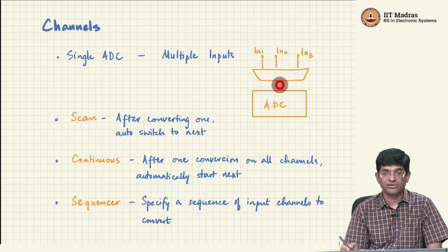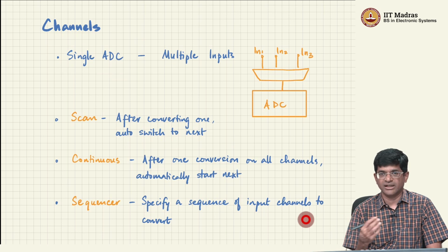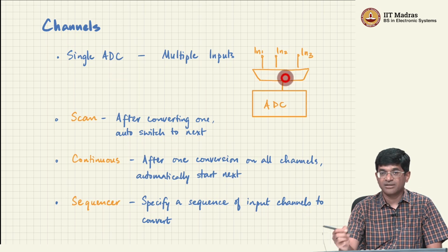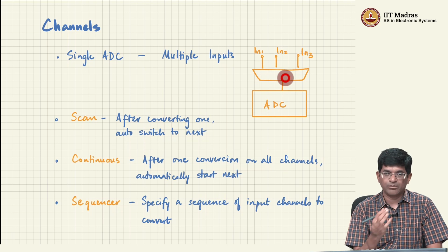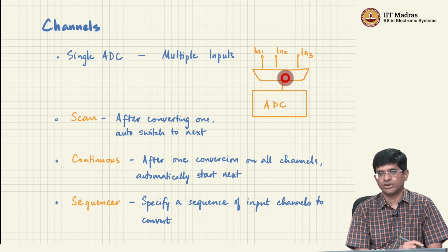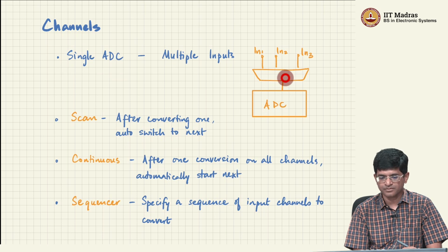But for applications like software defined radio or other things where your sampling rates themselves are very high, the difference in time between different samples might be on the same order as the sampling interval itself, which means that the time instants at which you are getting your data are sufficiently different that you need to compensate for that in your algorithms.